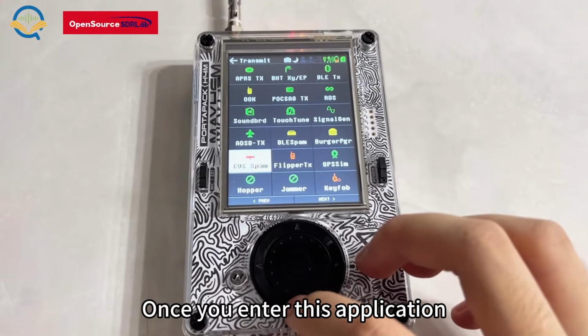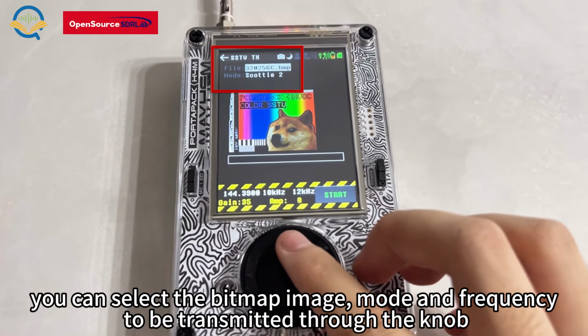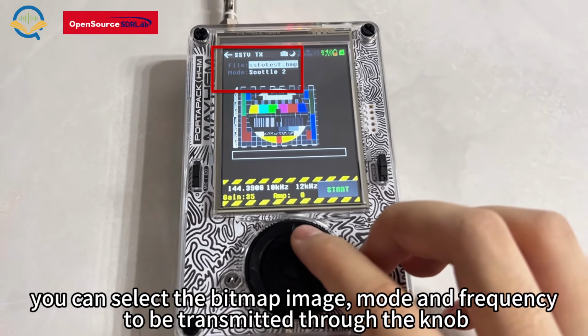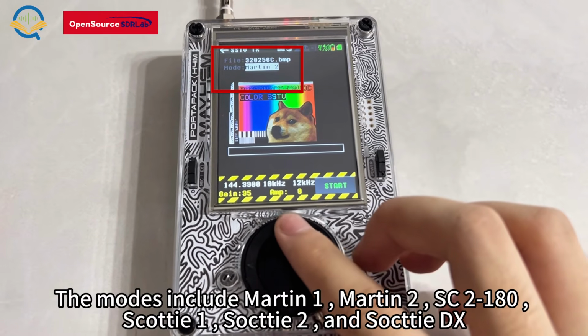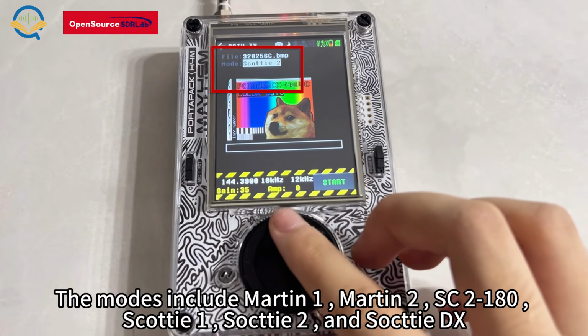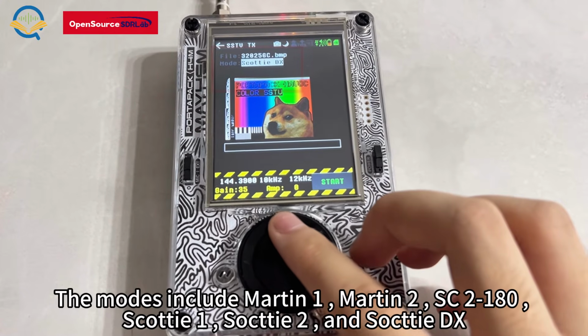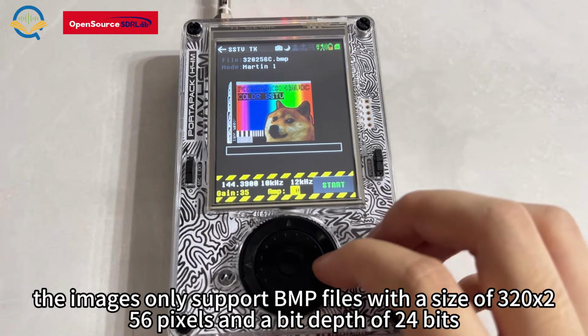Once you enter this application, you can select the bitmap image, mode, and frequency to be transmitted through the knob. The modes include Martin 1, Martin 2, SC2, 180, Scotty 1, Scotty 2, and Scotty DX. It is worth noting that in this application, the images only support BMP files with a size of 320 by 256 pixels and a bit depth of 24 bits.